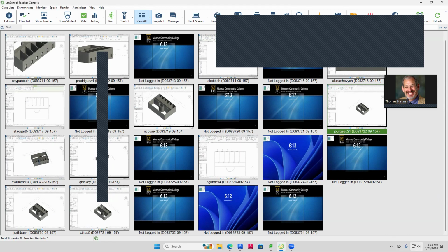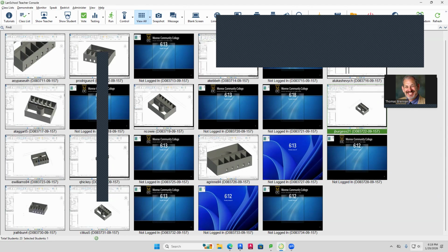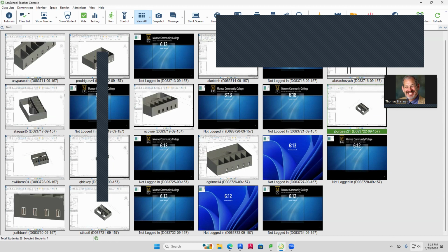Now that we've done that, if you could all take a look at that in 3D so I can verify you all got that. I'm just waiting on you guys. If you got that done, take a look at it in 3D and rotate the building so you can see the windows from the outside. To rotate the building, you hold down the shift key and then you hold down the middle mouse button. Perfect. Thank you. Looks like you guys all have it.